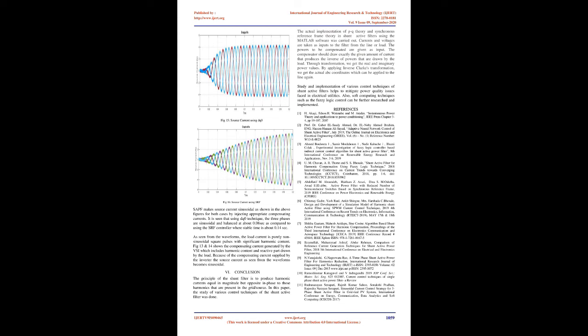Results and discussion. Source current using SRF. SAPF makes the source current sinusoidal, as shown in the above figures for both cases, by injecting appropriate compensating currents. It is seen that using the DQ0 technique, the three phases are sinusoidal and balanced at about 0.08 seconds, as compared to using the SRF controller, where the settling time is about 0.14 seconds.